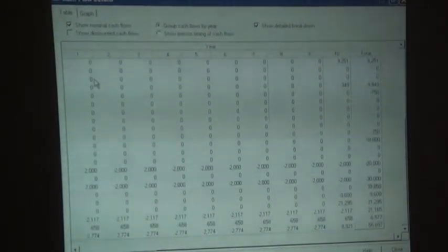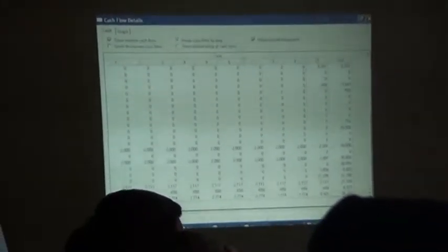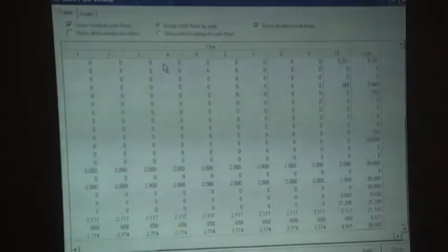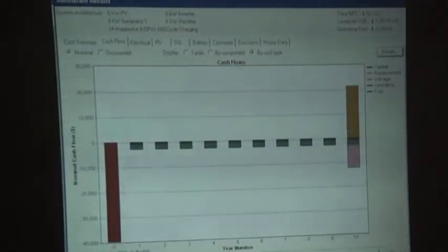So this is one of the good ways of bringing the technical solution plus your financial cash flow through this HOMER dimensioning. What we usually do is copy all this cash flow information and paste it in an Excel sheet to create a good, comparable business case. Or you can just click on this report, XML report. It can generate XML or HTML reports. The overall solution can be generated in one HTML or XML based report, which is quite nice and presentable.